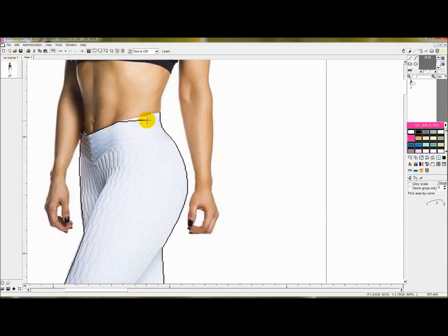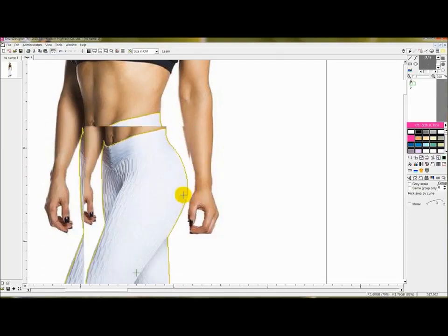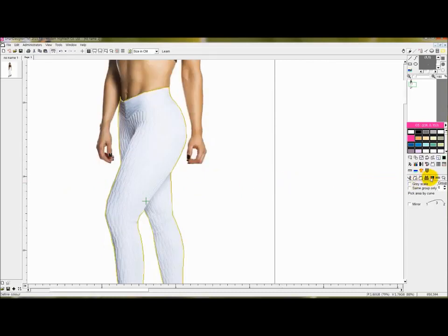So we're almost done. And once you're done, click the right mouse button and click OK. And then I'll let you know how to do the 3D draping. Click this button and click inside of it and click the right next button and then draw the straight line. This is the direction of the pattern, so I'm going to just let it be horizontal. And then type the pattern size. You can change it later very easily, so just give some random size. I'm going to give 10 and click OK.